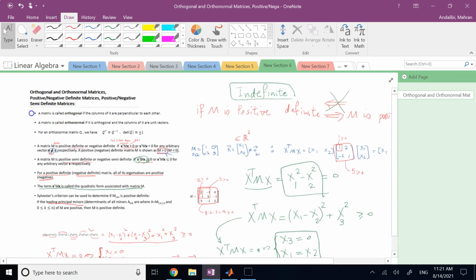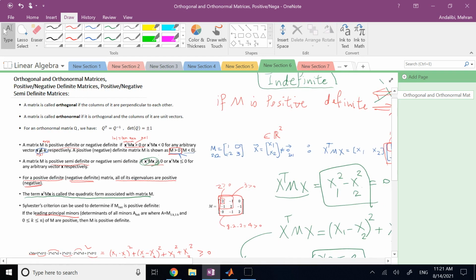So I showed you the definition of positive and negative definiteness, and I showed you 3 separate ways to determine them. One using the quadratic term, one using the sign of the eigenvalues, one using the Sylvester criterion. All 3 of them can be used. So hopefully this video was useful to you. Again, where would you use this semi or positive definite and so on? Mostly it is in controls, mostly in linear, and also definitely in nonlinear controls in what we call the Lyapunov functions and so on. We definitely use this for stability of nonlinear systems.